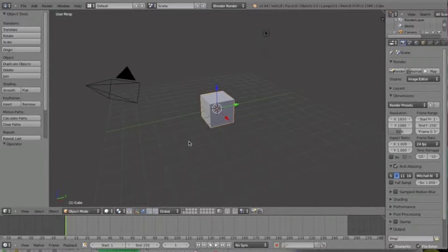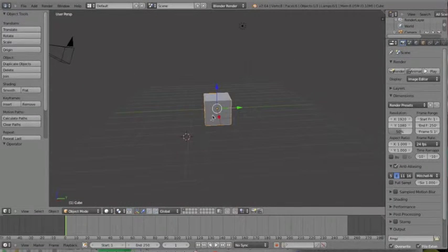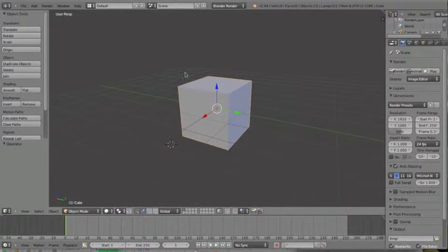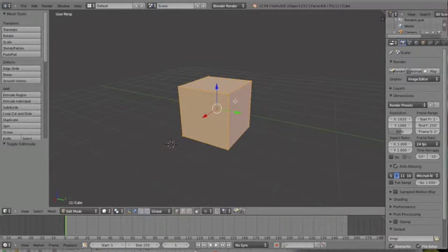You may realize that when you select the cube, you are changing the entire object. In Blender, the mesh is made of smaller parts called vertices, edges, and faces. Now if you look down here near the manipulators, you will see it says Object Mode. This means that it is taking the object as a whole. Click on this and change it into Edit Mode. You may also just press Tab on your keyboard to go between one another. This will allow you to choose single vertices, edges, or faces without selecting the entire mesh.